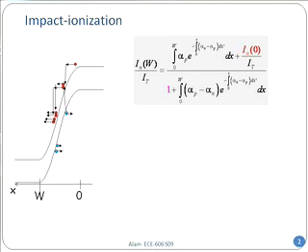And then, of course, I_N(W) is the total amount that is getting out from the left-hand side after all this avalanche multiplication. Immediately you realize I_N(0) is very small, I_N(W) is huge, right? Because of all this impact ionization process going on. Okay, and alpha_n and alpha_p, you remember, what are these? These are impact ionization coefficients.